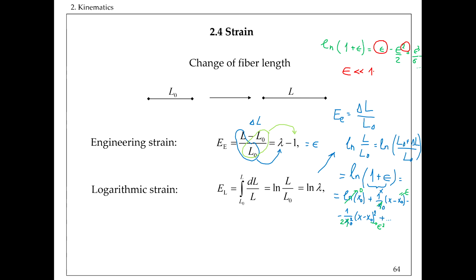So this is just to illustrate to you that, okay, they are of course connected. And this logarithmic strain basically reduces to engineering strain when deformations are small, but it becomes less accurate to use engineering strain if the deformation becomes larger. So you do need this nonlinear higher order term to more accurately describe the relative changes between the positions of points. That's what at the end we want to measure with the strain.